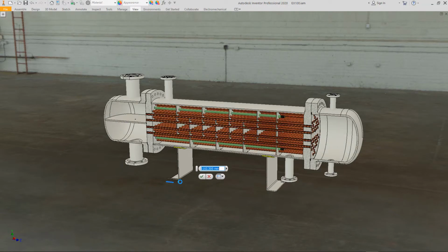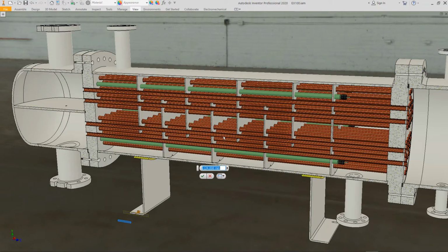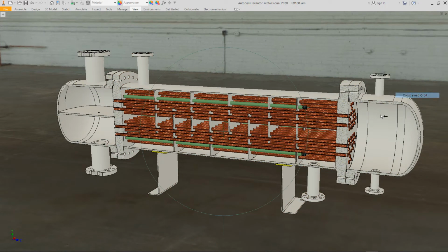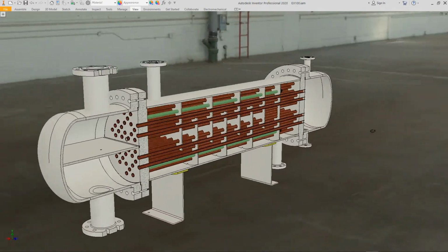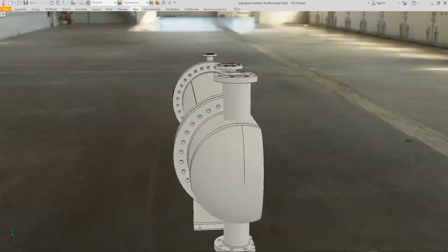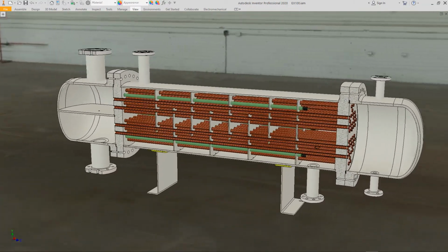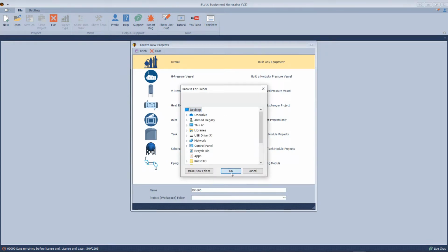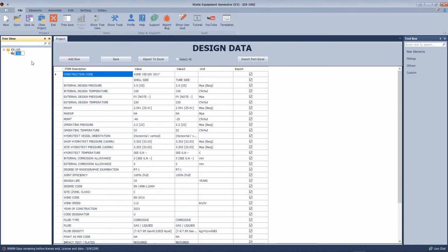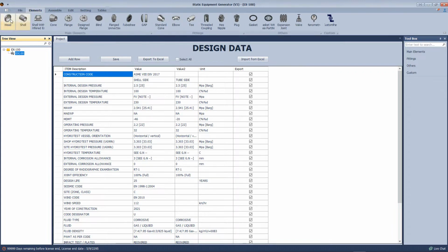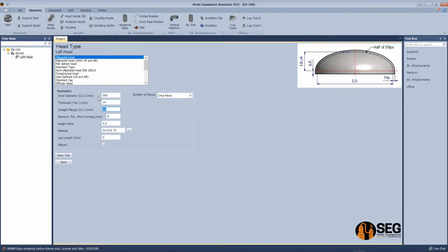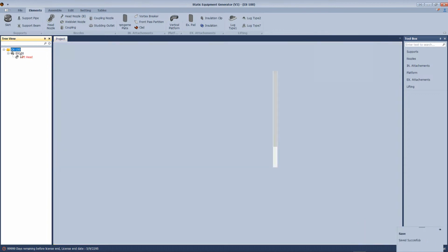In this tutorial video, we will learn how to create a BEM exchanger type and how we can create the tube bundle simply. Beginning, we will create a project and select the module. After that, we will create the channel head, define the inside diameter and straight flange thickness.